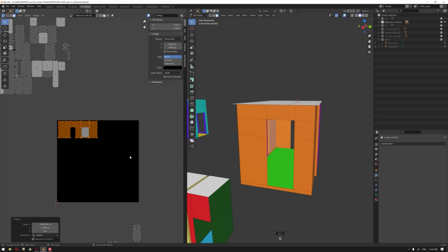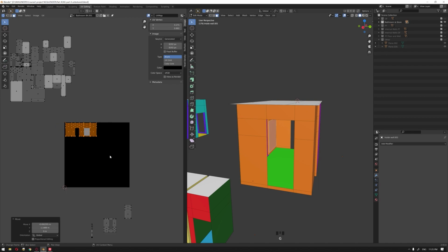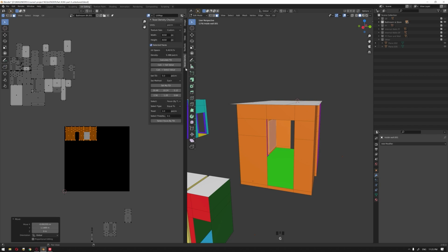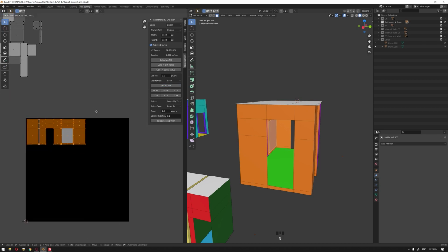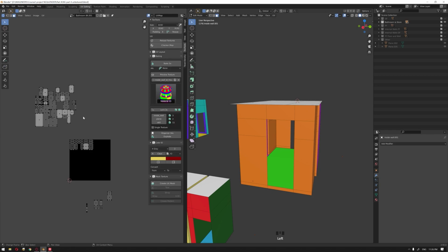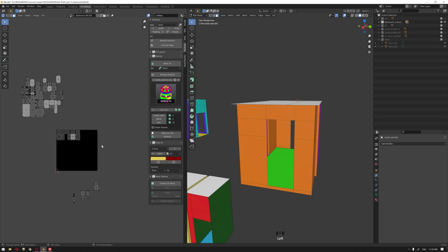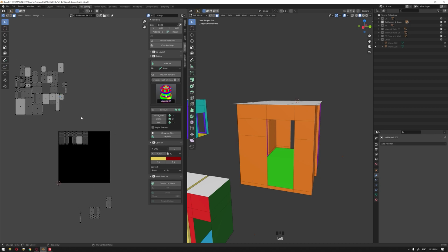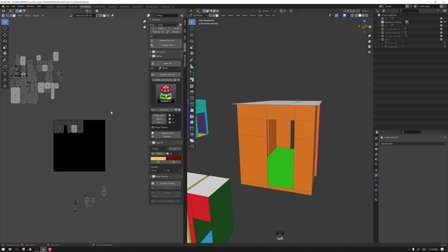After we move all the bathrooms, we can go again to the texel density and choose the texture size, and make sure, for example, that we set the texel density to a higher value. Let's say, for example, 8, so we can get the best out of our Quixel Mixer texture resolution. After we finish that, we're gonna go to the text tool, and then we're gonna pick our texture as we did before in our previous tutorial to create the material ID. So I'm gonna skip this step because we did it before, and then we're gonna move to Quixel Mixer.